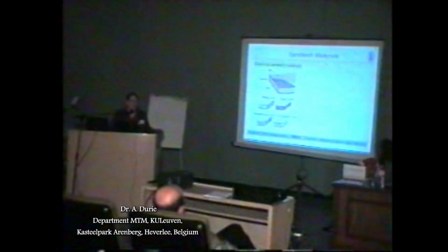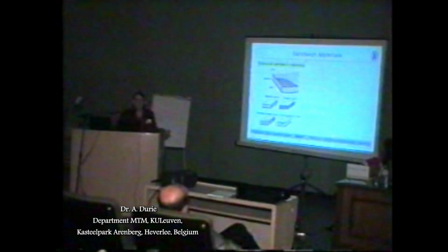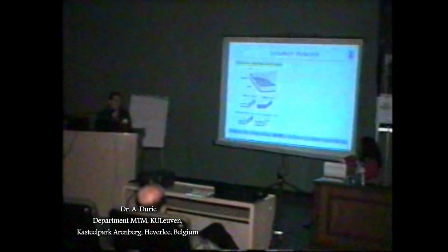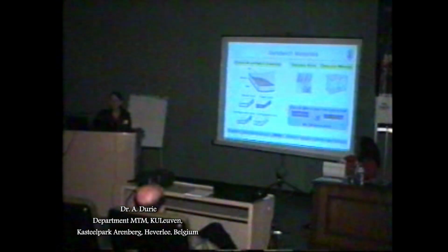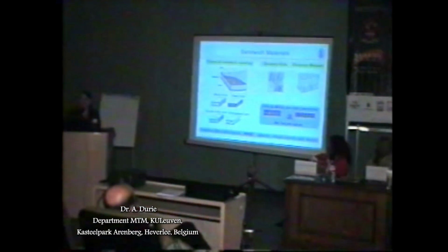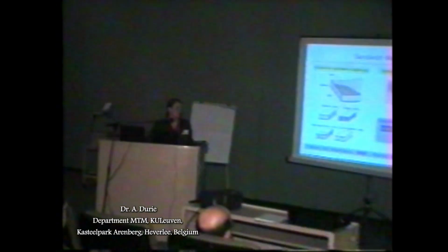The main problem with these, as I said before, is delamination. So it's actually the surfaces coming off the core material. And our solution was to use integral double layer fabrics, distance knits and distance weaves, to try and make these properties a little bit better through thickness strength.